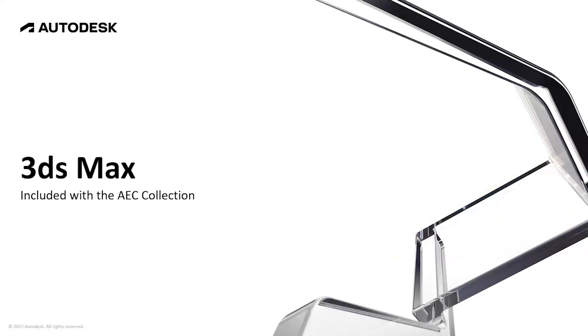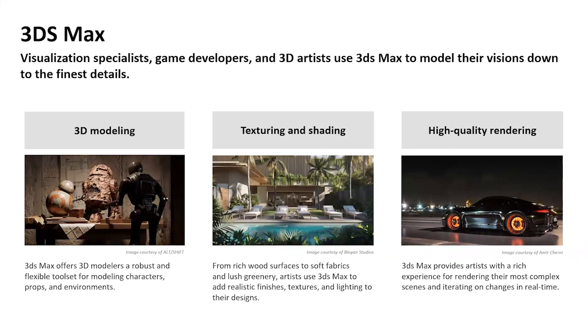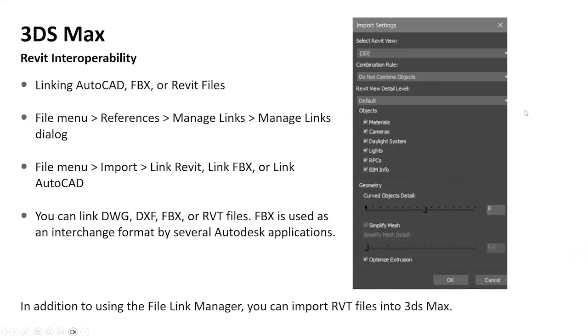3D Studio Max is also included with the collection. As you may already know, 3D Studio Max is the visualization tool for gamers and artists and you name it. So take your models directly in, texture, shading, do high quality rendering. When you bring in geometry from places like AutoCAD or Revit files, we have the opportunity of using an FBX file. The reason why I mention FBX is because you could bring in the entire Revit model or the entire AutoCAD model, but you also may just want to study or render a room or a section of the room or a corridor.